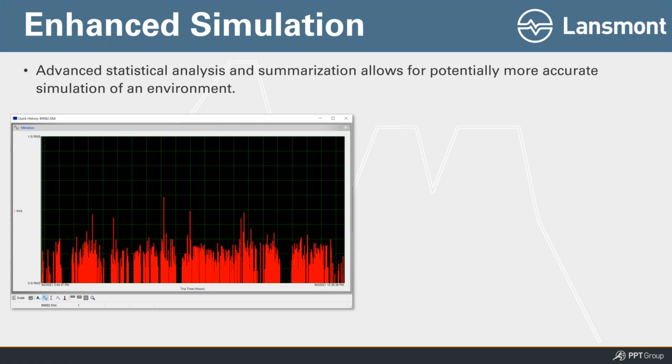And so what's important to realize is that if I do that summation average across all that data, which could be thousands of events, the average GRMS, because that's the Y scale here, 0 to 1 GRMS, the average intensity that we would get in this case is about 0.157 GRMS, which is where I drew the dotted line across the data there. So that's fine, that's what that means.